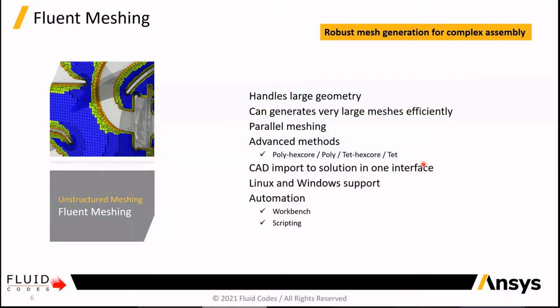you were doing a transformation, transforming the tetrahedral mesh to polyhedral mesh. That was an additional feature you were using before performing the simulation, done by Fluent before starting the simulation. Now what Fluent Meshing is giving you is the opportunity to generate native polyhedral mesh. So you generate the polyhedral directly starting from the geometry. You fill up the volume using polyhedral cells from the beginning. So this is a big advantage.